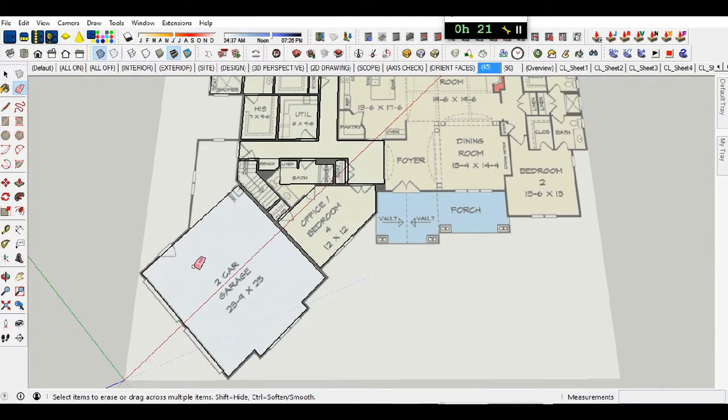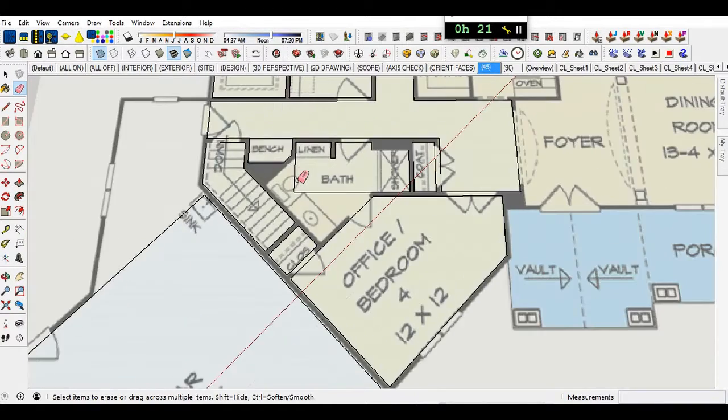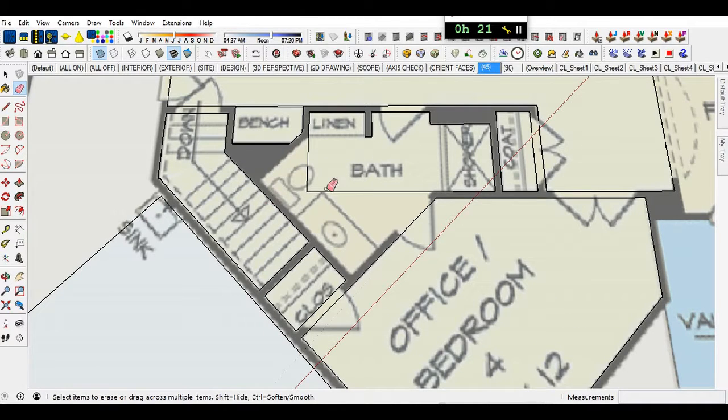So you're going to drag up and down until these two sides land in the two corners they need. And then because you lined up this side, all you have to do is use the line tool and reference off of the line itself.